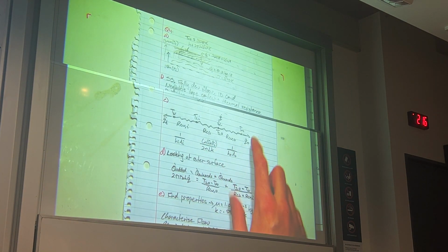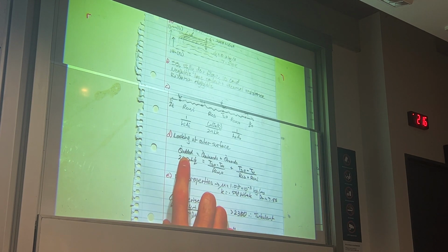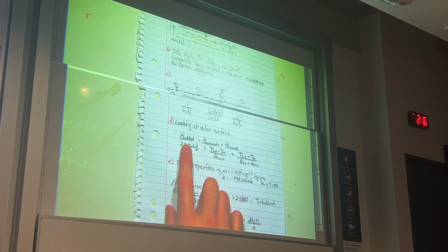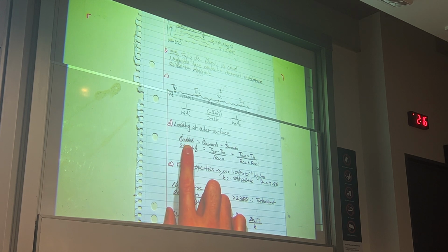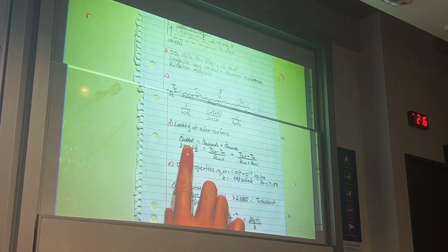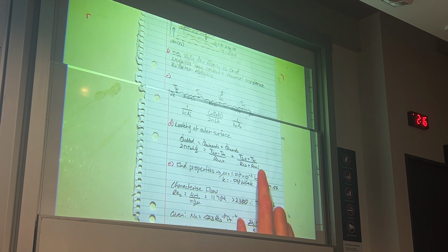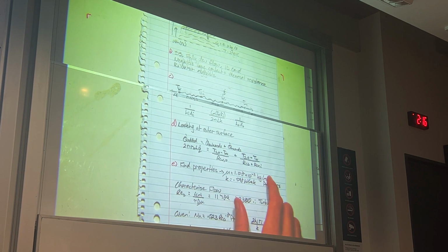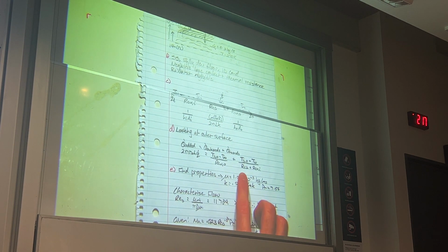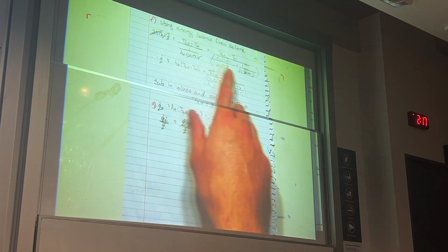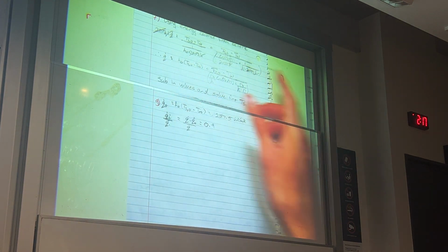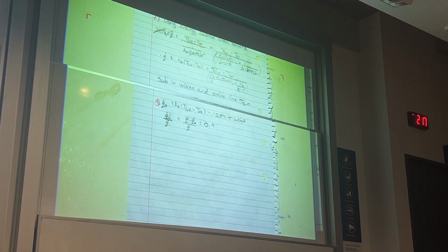Oh, this energy balance. So through our thermal resistance network, I came up with this energy balance here, which was like the amount of heat added is the sum of the heat that ends up getting convected outwards and convected inwards through the pipe, which comes out to be this. And we've solved for these resistances in part C. So all I did was I took that equation and I just plugged it in. And then through some manipulations with some of the common factors, I've cancelled stuff out.